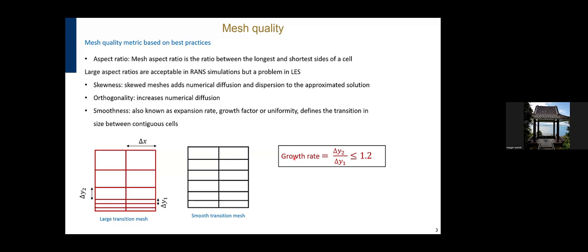And if you do work on any CFD simulation, you need to report this metric, because this metric would end up being something that your solution will be judged against. So if, let's say, your mesh metrics are bad, then your solution typically would go along with it. So this is something that is really important that you need to take care of.